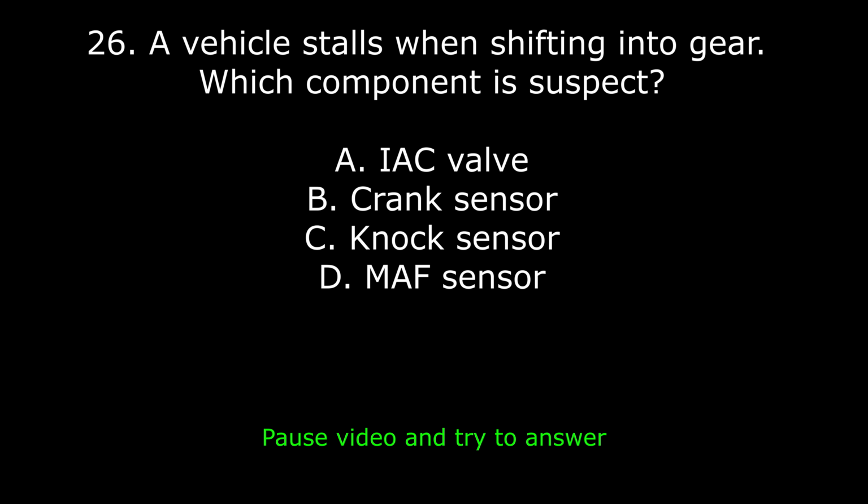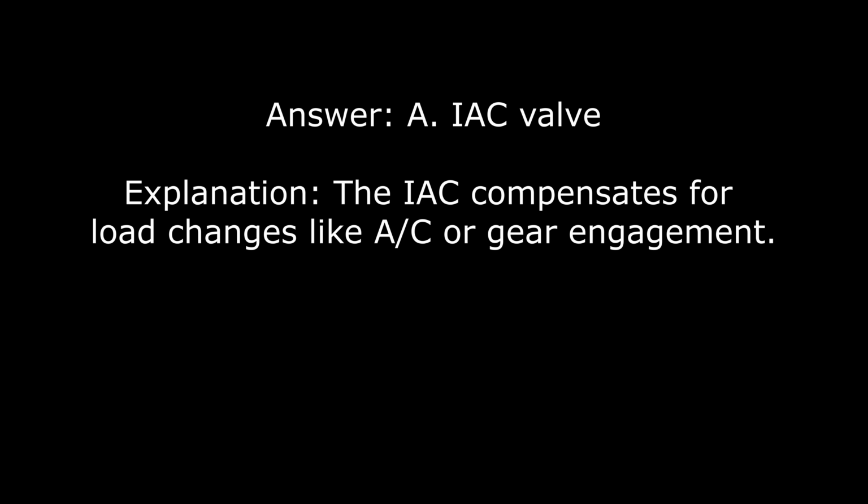26. A vehicle stalls when shifting into gear. Which component is suspect? A. IAC valve, B. Crank sensor, C. Knock sensor, D. MAF sensor. Answer: A. IAC valve. Explanation: the IAC compensates for load changes like AC or gear engagement.